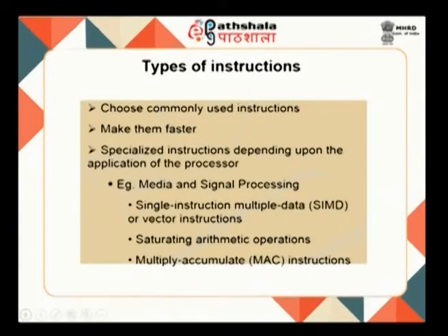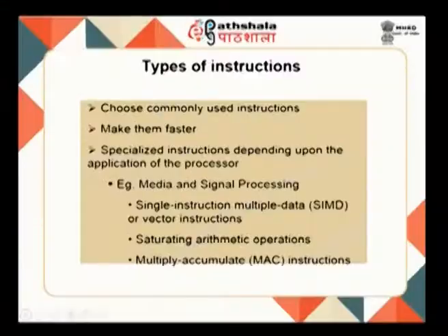So, examples of specialized instructions may be media and signal processing. When you are looking at media and signal processing, you may have to bring in SIMD type or vector type of instructions which try to exploit the data level parallelism, where the same operation of addition or subtraction is going to be done on different types of data. And then you may have to look at saturating arithmetic operations, and multiply and accumulate instructions. So, you either look at a general instruction set or you also include some specialized instructions based on the applications that you are targeting.